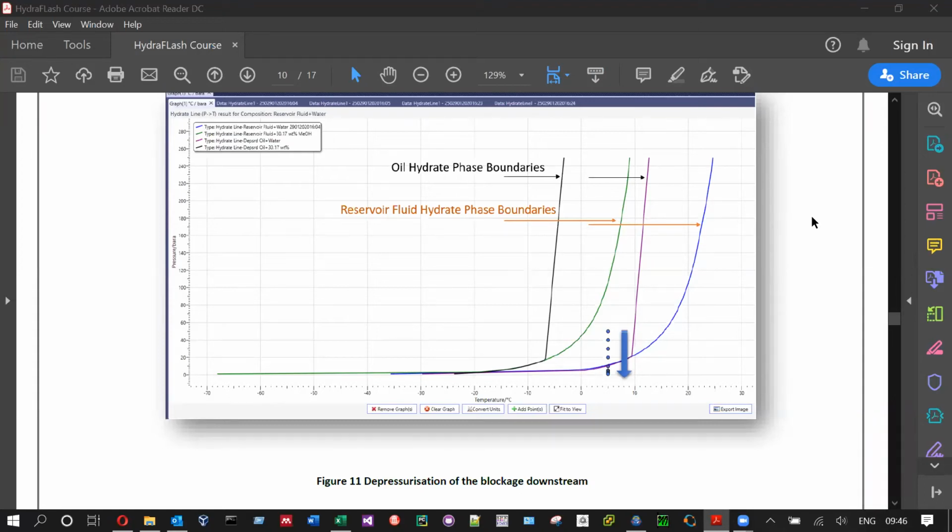The reason is that hydrate needs around 15% gas, while the gas dissolved in water is less than 0.1%. So the interface is where the gas gets into water and forms hydrate. So the fact that methanol is lighter than water, and if it's not properly mixed, is to our benefit.